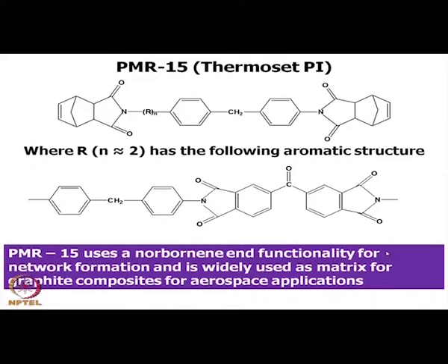So it appears that these polyimides, Kapton or the different thermoset polyimides, as I have shown you with the structures and formulas, are very high performance, strong, thermally stable, with high strength, high impact resistance and high flame resistance. They serve as matrix resins for making composites used in aircraft structures or aerospace structures.